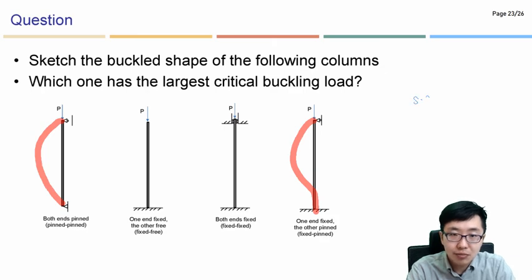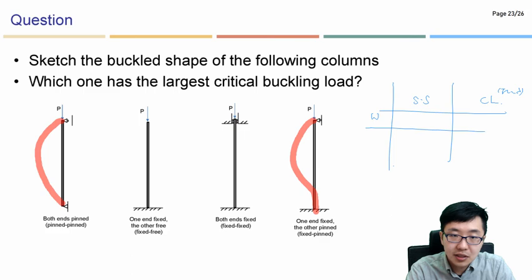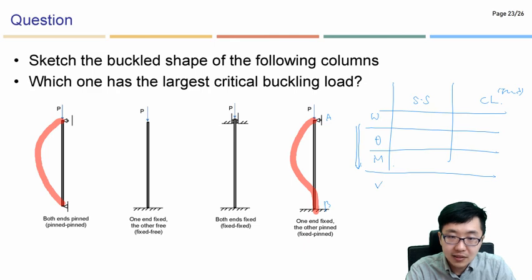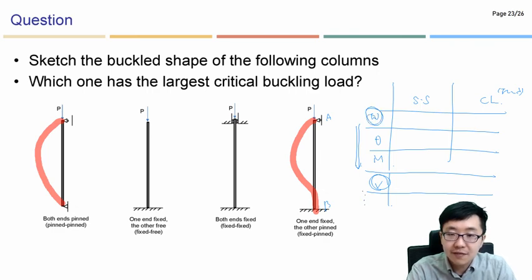And in the previous topic, I briefly introduced boundary conditions by using mathematical formulations. Again, simply supported and clamped condition or fixed. Like deflection at here A and B, and slope and moment. If we go further, we can see like here, this is shear, and furthermore. So deflection, that should be 0 and 0. Slope, in this case, slope is unlimited, and in this case, we don't allow it.